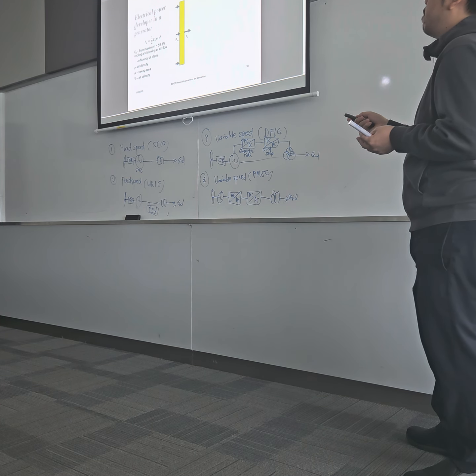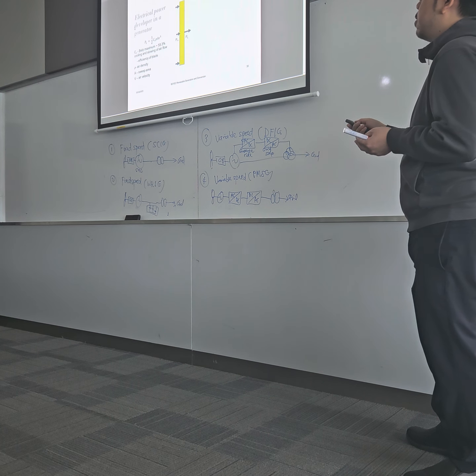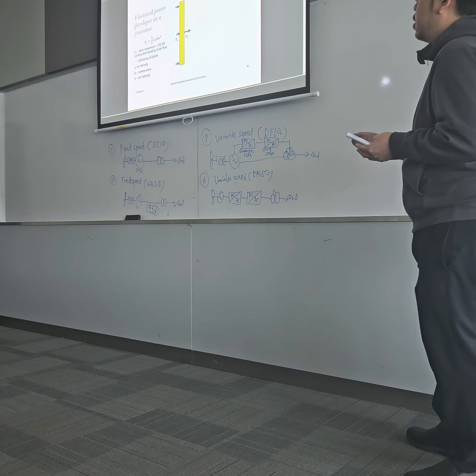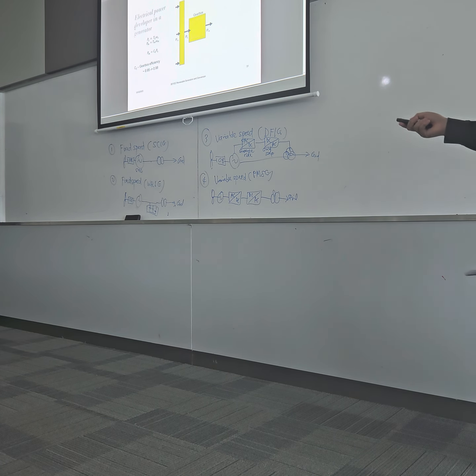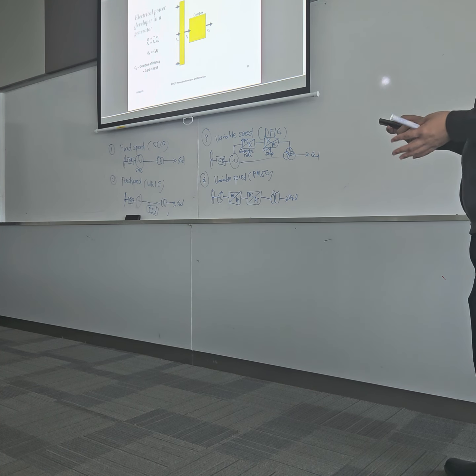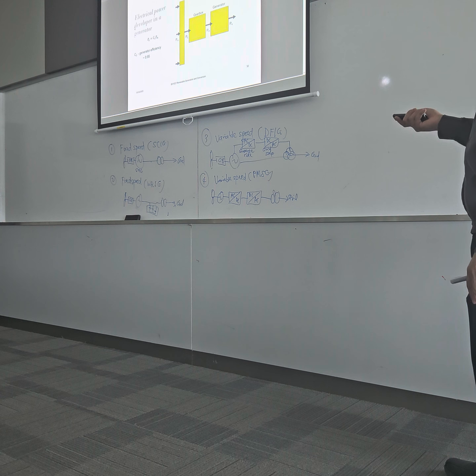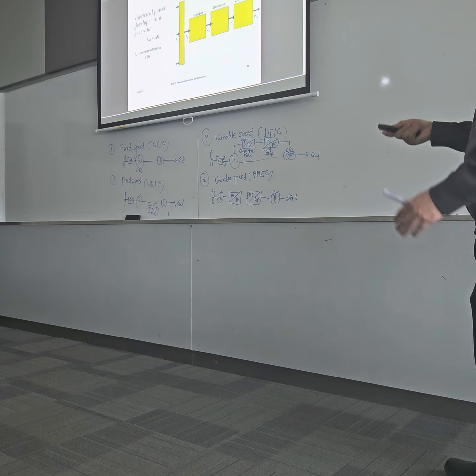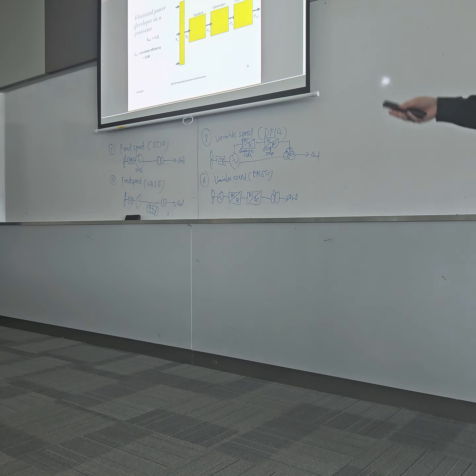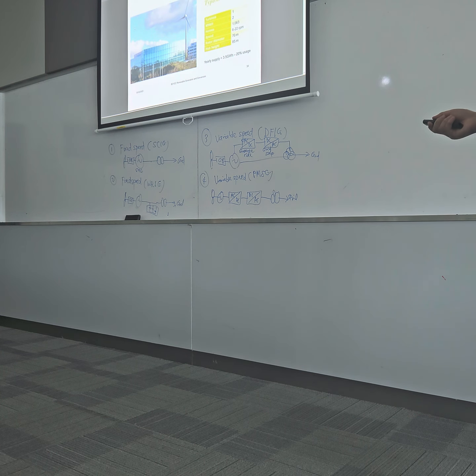Your input power in the turbine is governed by the Betz limit, so it's only 59.3% maximum efficiency, followed by the gearbox, which also has an efficiency of 0.95 to 0.98, then the generator, another drop of 5%, and lastly the converter, which may also be about 4 to 5%. Overall, you will have losses along the way, in each component. So depending on what the question gives you, you may have to account for these losses altogether.